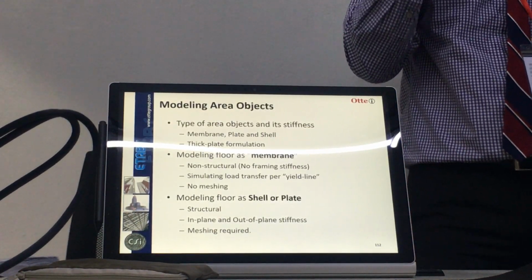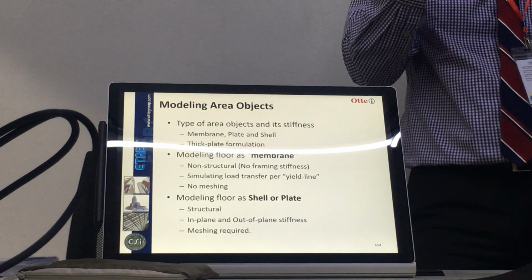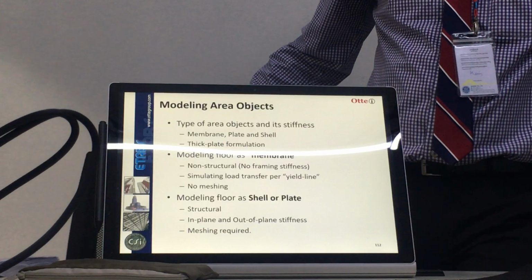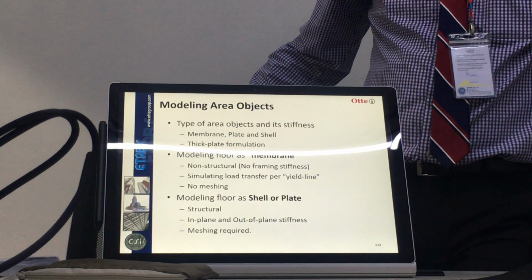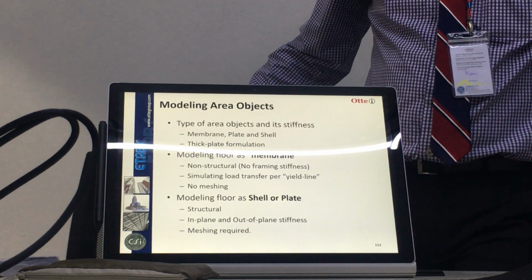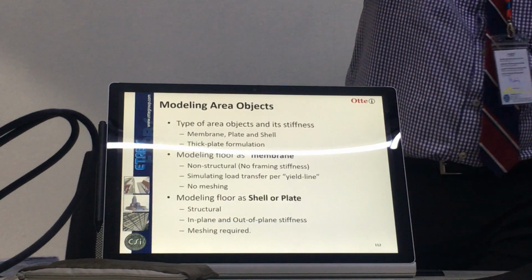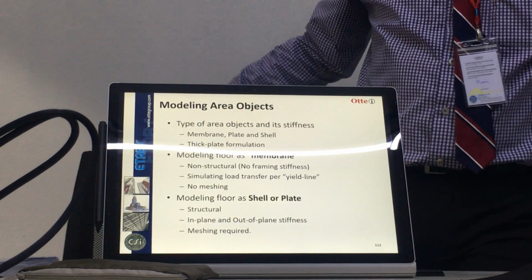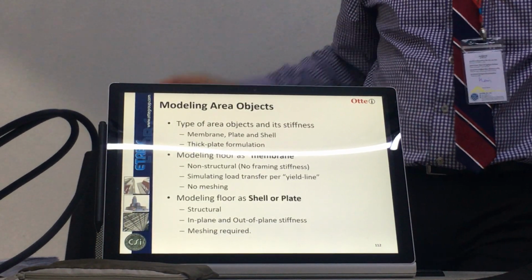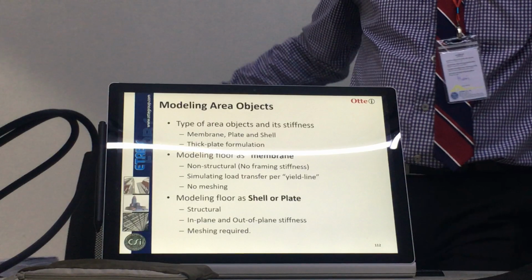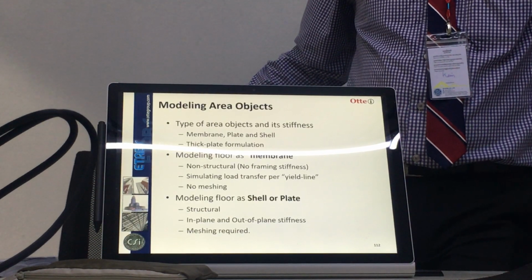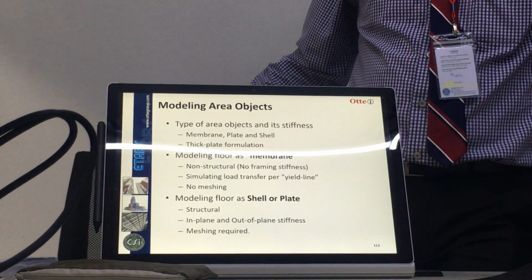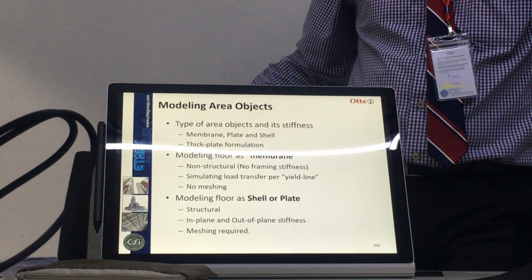So as engineers, we need to choose the right element. I had an engineer who called me up and said, I need to use solid element in my bridge. But solid element doesn't seem to give me the result I get when I put in tendon. We don't formulate the time-dependent property for the solid element. It's not inside, but for shell we have. And he said, solid is the best element. I have to use solid because it's better than shell and better than frame.